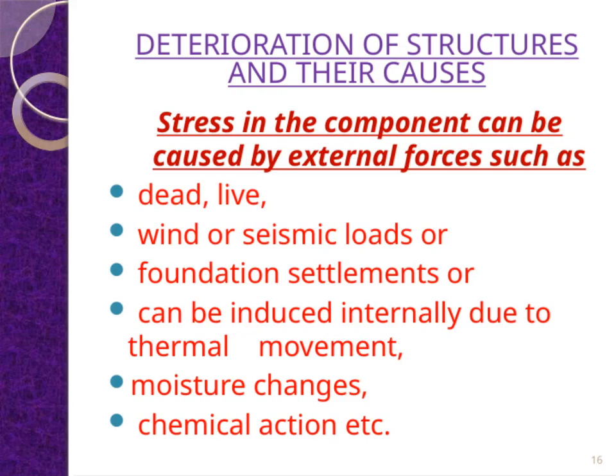Stress in the component can be caused by external forces such as dead loads, which are the permanent weights of the structure itself, and live loads, like the weight of people, furniture, or equipment that can vary over time. Wind or seismic loads also play a significant role, especially in areas prone to earthquakes or strong winds. Additionally, foundation settlements, which occur when the ground beneath a structure shifts or compresses, can introduce stress as well.